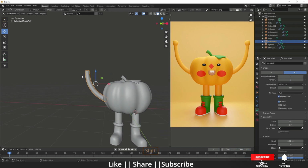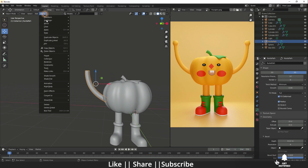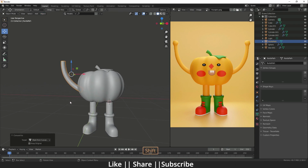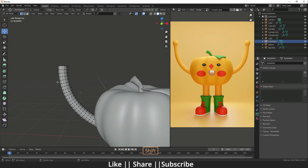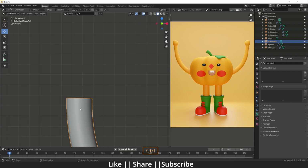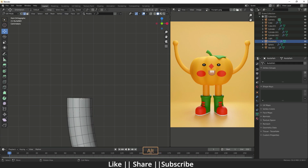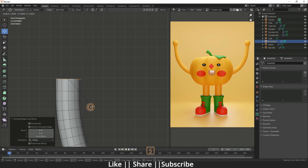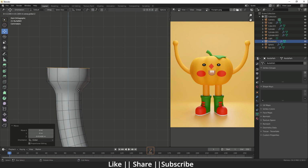And then we'll convert this part to the mesh, something like this. And then I'm going to do some editing. So first of all, we'll add the subdivision modifier on it, and then we'll select this edge and extrude it, and then I will just scale it something like this. We can scale one more time, and we'll do one more time.